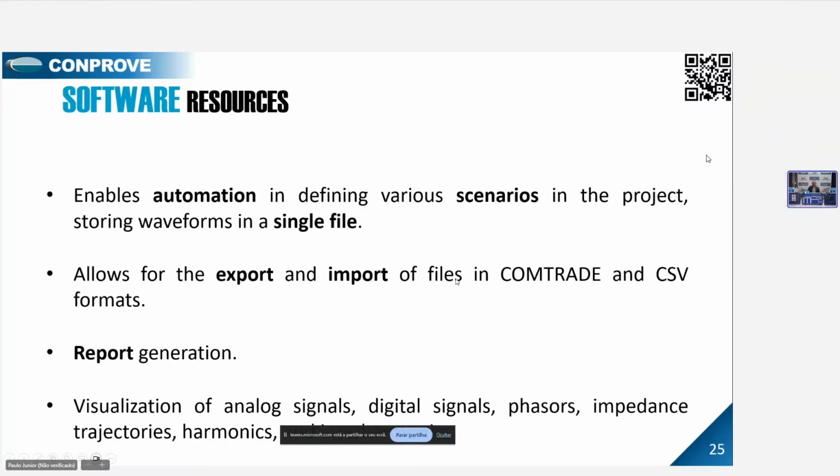We can export and import files in COMTRADE format, CSV format, and PCAP files that can be imported from Wireshark or another traffic monitor. We can generate reports with the tests and visualize all signals: analog signals, binary signals, phasor, impedance trajectory, harmonics, and interharmonics.